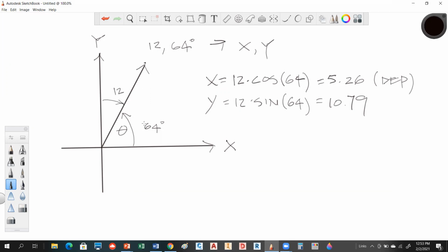Okay, so you've got to be careful because I'm doing the right thing, but I've got to make sure whether that angle is measured off of the horizontal or off the vertical. So remember, in this case, X is actually departure, and this one is actually latitude. But if you go back and look at my latitude definition, I said latitude is distance times the cosine. And that's true, but the angle is measured here, not here. Okay, does everybody get what I'm saying there?